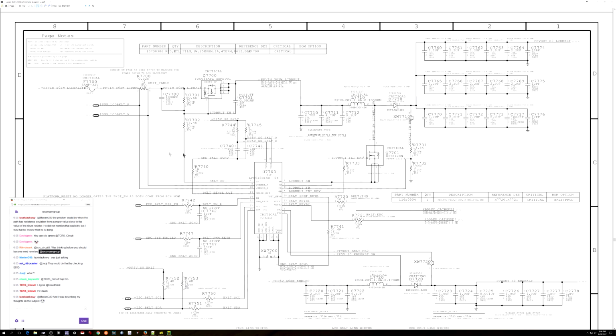So, this is our LED driver section. The fuse is fine. The current sensing traces attach perfectly to our LED driver. The current sense resistor is fine. This transistor was not opening before because the voltage divider that opens the transistor did not have a path to ground.